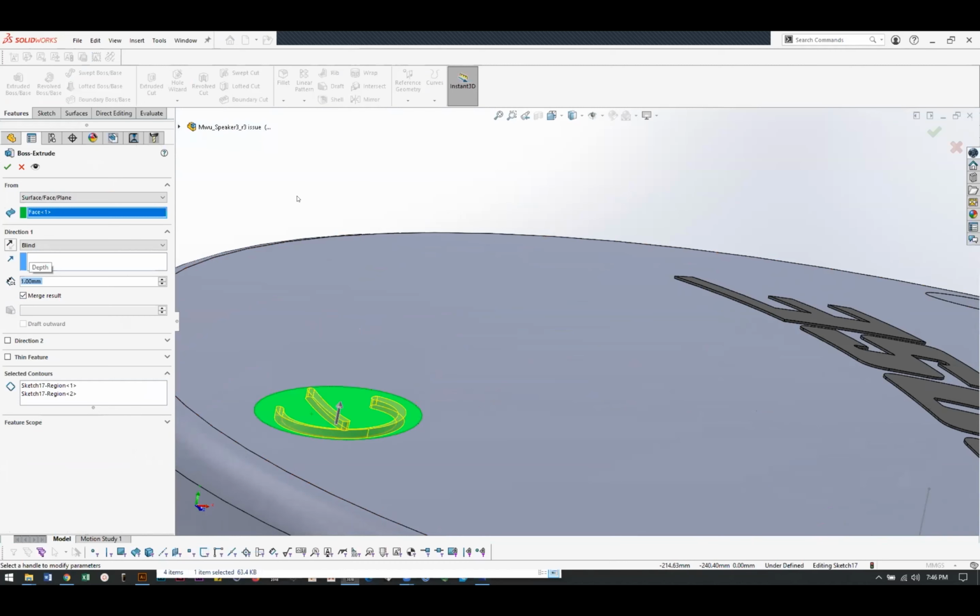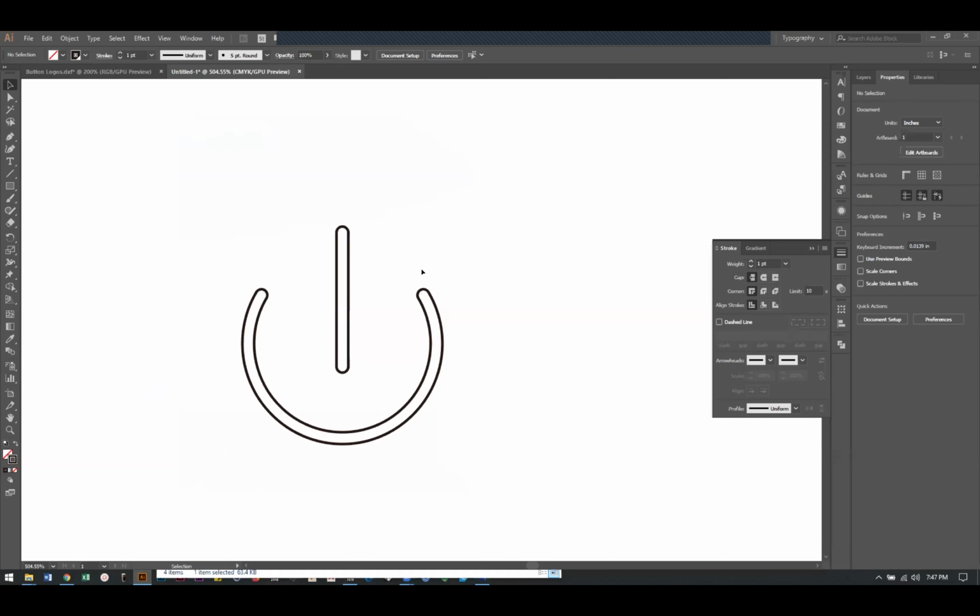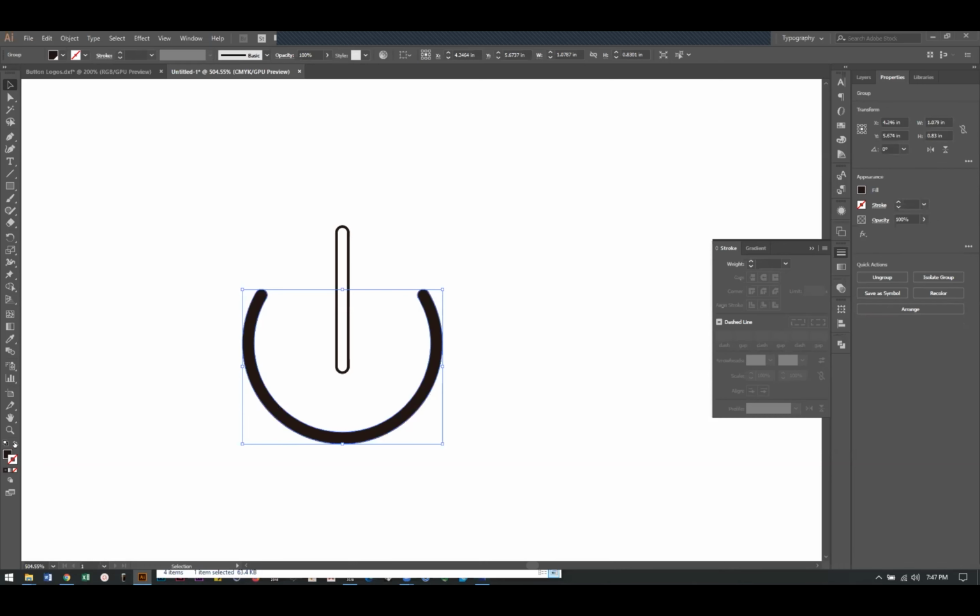So it looks like the issue here is that there's something up with the line work back in Illustrator. Let's just jump back over to Illustrator and look at this thing. Since I wasn't here to see you make the line work, I can't say what happened, but we started to get an idea of how to fix it when we found out that you could change this to a fill and there was no issue.